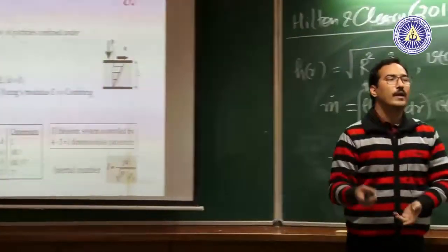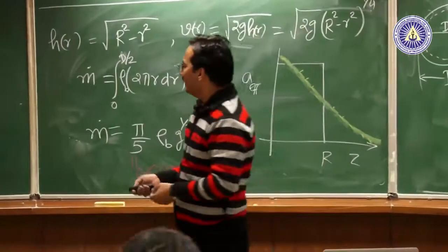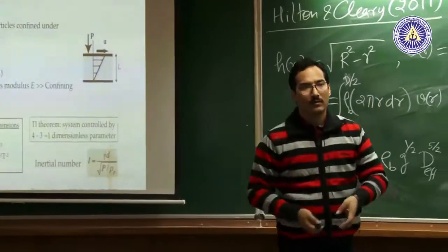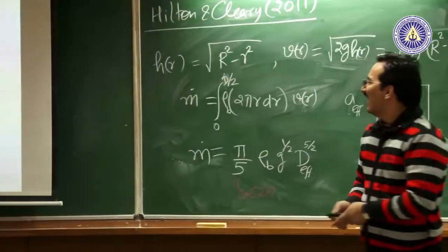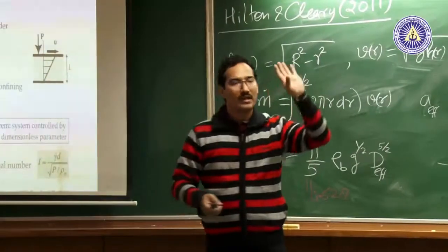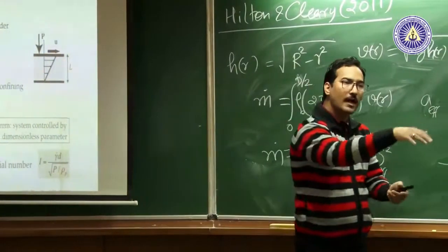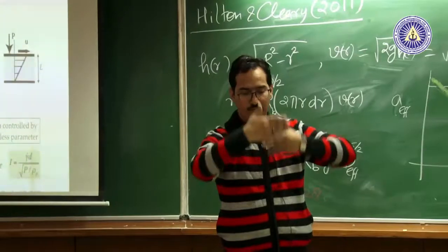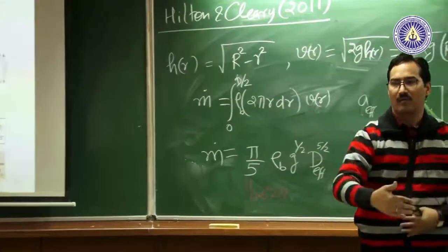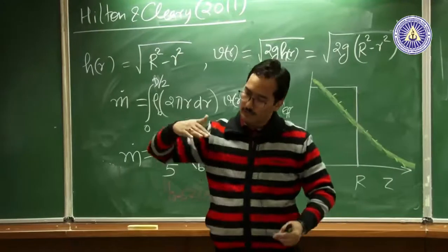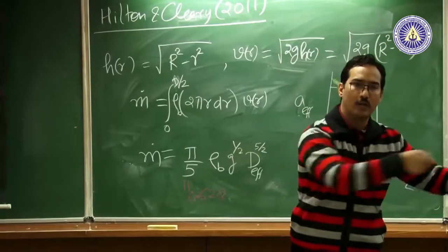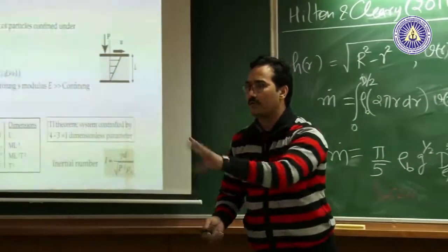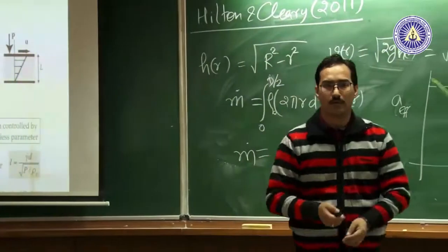This is the typical shear flow experiment that you would do in a fluid. The only thing you may not be too concerned about is this pressure part. In this case, we are talking about dry grains. Think of sand or glass beads between two plates, make a band of them, with very little effect of the front wall, for example, and you have a top plate which is moving, you apply some pressure on top of it and then you move. Once you move, the entire material in this can move, and this is the canonical, typical plane shear geometry that you can generate.